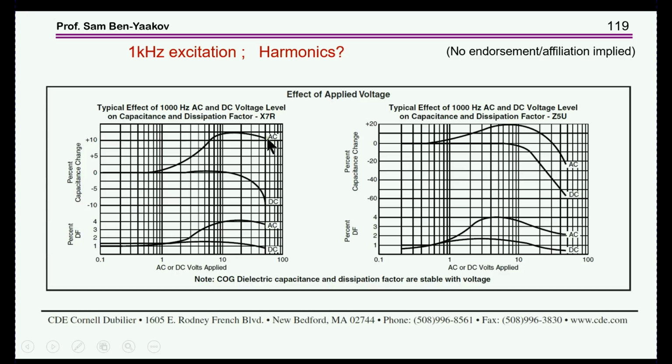But what I'm interested in is this part, and what you can see is that there is an increase in capacitance. This increase we talked about, this is the very beginning. Here it's up to 10 volts, and then it goes up. This was measured with a signal of something like 60 volts, looking at the actual equivalent capacitance, that is current and voltage and the ratio between them for the given frequency.